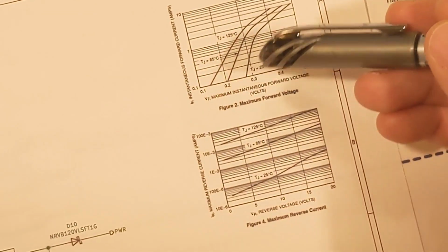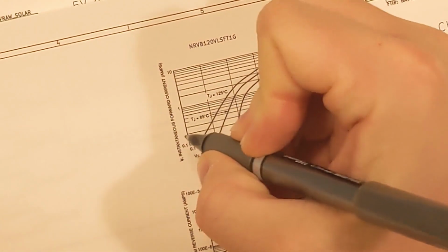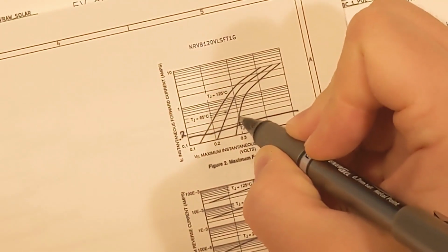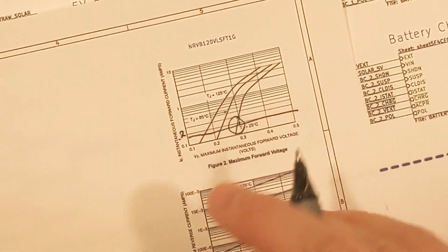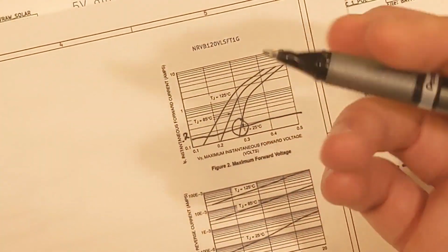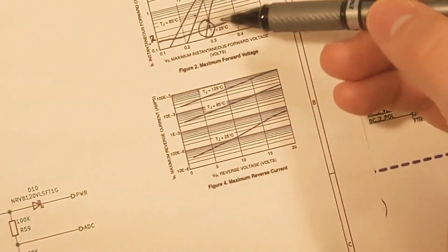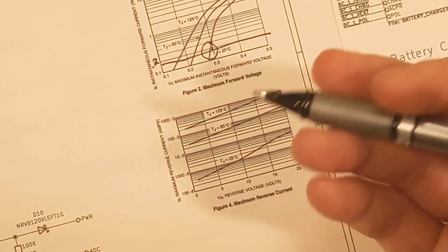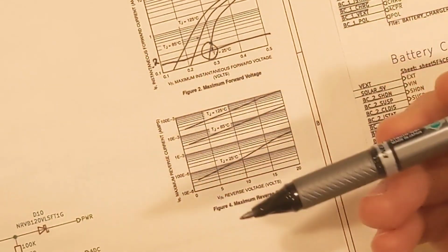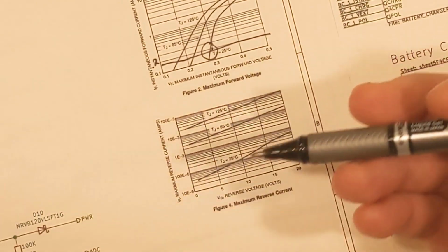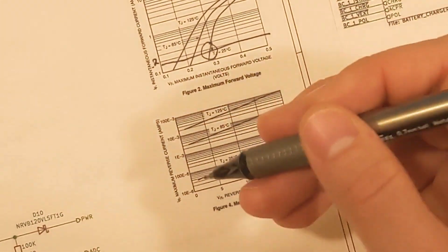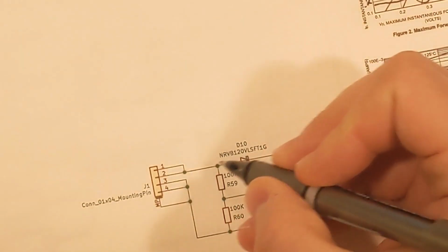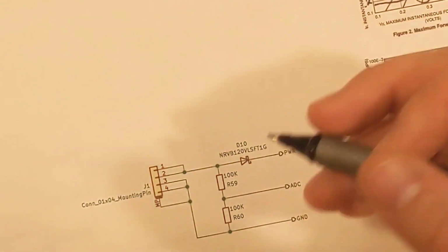And to touch briefly on the diode, if we're operating at 0.2 amps on this line, then at room temperature we're close to nearly 0.3 volts of forward voltage drop, which is unfortunate but necessary when dealing with these sort of diodes. I tried to strike a balance between getting this as low as possible and the reverse current of the diode, since there will necessarily be some leakage back through the diode if this solar cell is in the darkness and other ones are in light. I want to minimize how much leakage is coming through here. And as this goes down, this goes up, and vice versa. So this NRVB diode was a pretty good compromise based on what I could find on DigiKey.